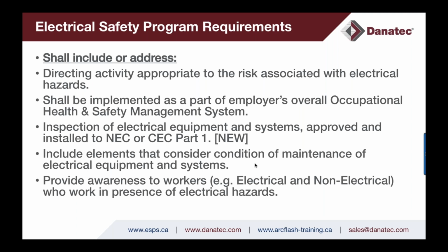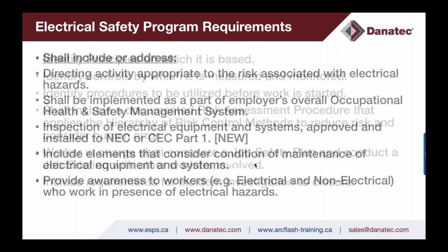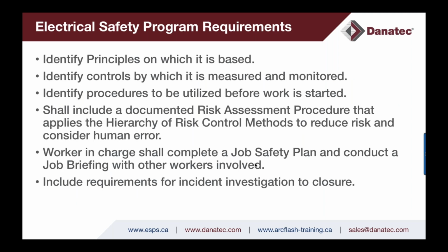So your electrical safety program, as the employer or the host employer, has to address not only electrical workers, but non-electrical workers. And again, non-electrical workers are predominantly exposed to the shock hazard with their use of portable cord and plug connected electrical equipment and the need to identify a GFCI to reduce the risk of shock.